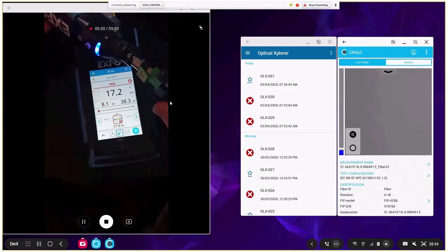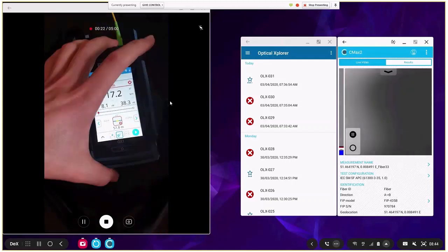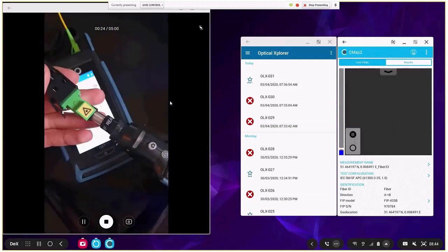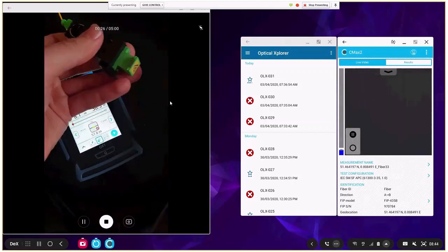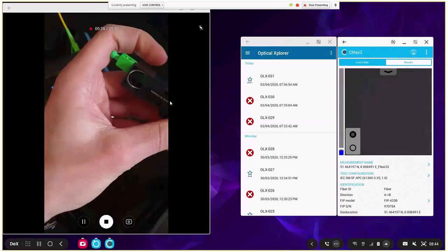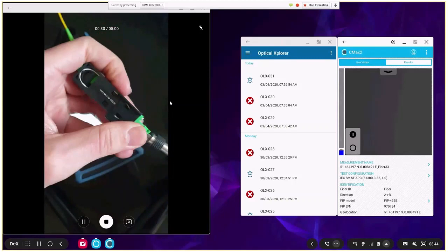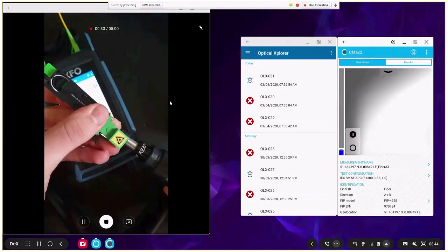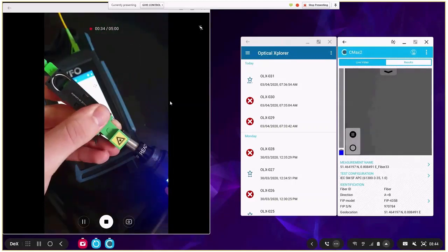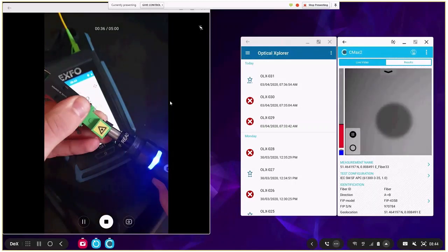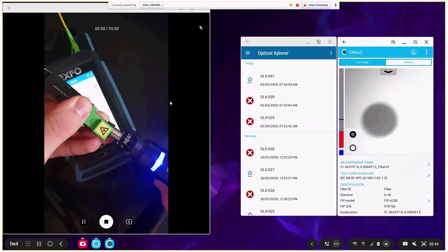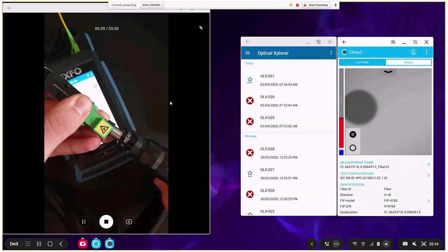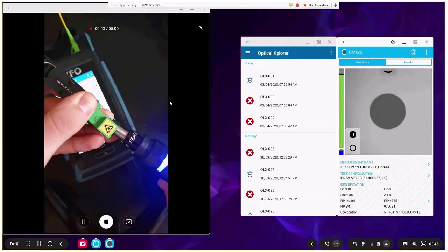Here I have it connected to my mobile, but if I don't have our fibers clean on our networks, when I go for high data rates, we are always going to have problems on the fibers, and it doesn't take long to inspect the connector. As you see here, just a few seconds, and we would have the acquisition.